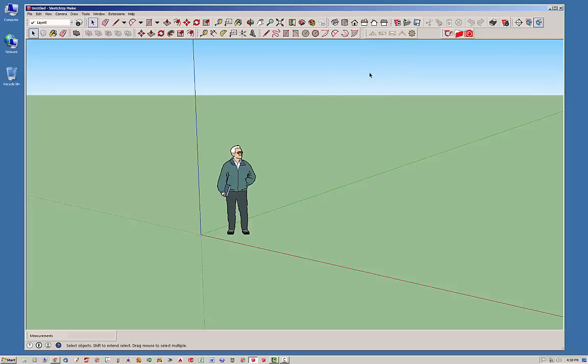So to start with, let's take a look at creating a basic truss. If you look at the icons up here, you're going to see this triangular truss icon. That's for all your basic truss types, your roof trusses. And then you're going to see the square truss icon, and that will be for floor trusses and floor joists like TGI joists. And in the future, I think we'll also add in some solid sawn joists as well. This one here is for drawing truss sets.